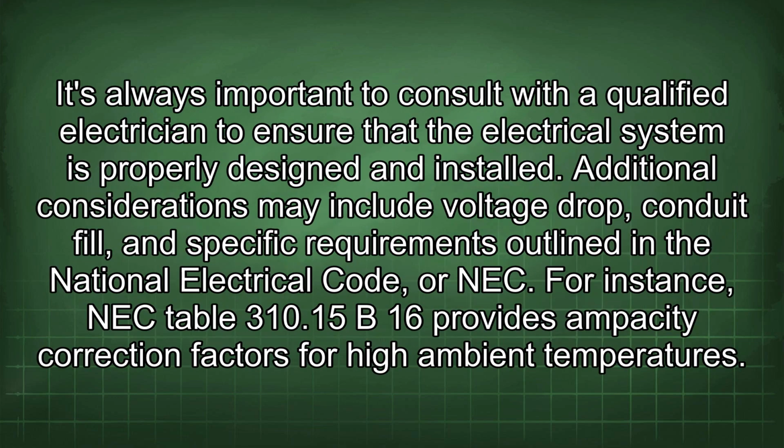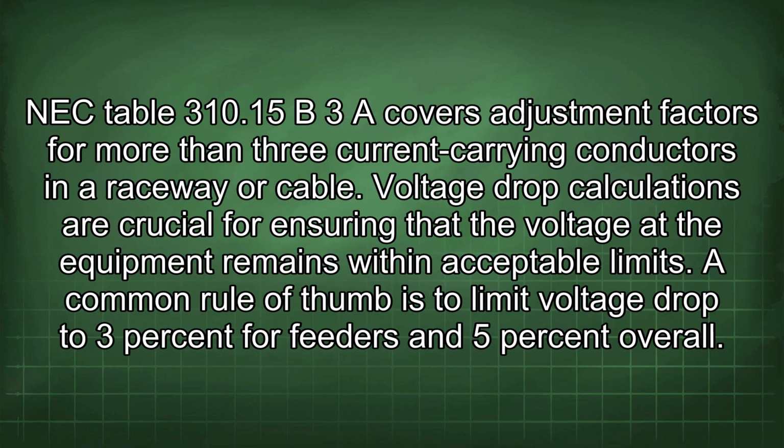It's always important to consult with a qualified electrician to ensure that the electrical system is properly designed and installed. Additional considerations may include voltage drop, conduit fill, and specific requirements outlined in the National Electrical Code, or NEC. For instance, NEC Table 310.15(B)(16) provides ampacity correction factors for high ambient temperatures. NEC Table 310.15(B)(3) covers adjustment factors for more than 3 current carrying conductors in a raceway or cable.